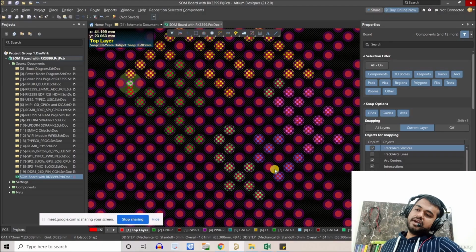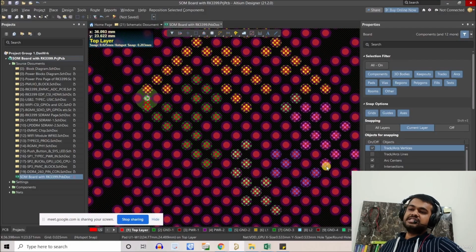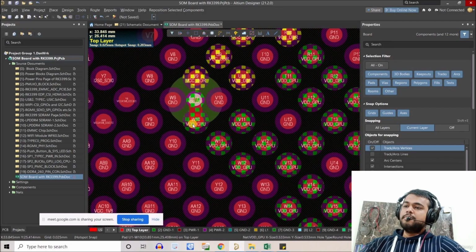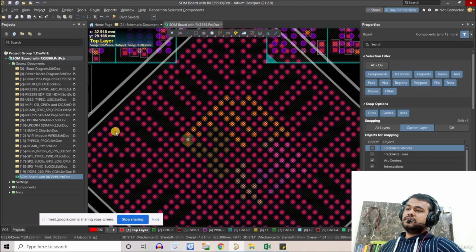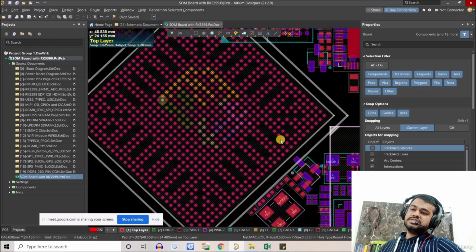So here we have fewer pads, only 6 pairs, but we have too many capacitors. In that case, we'll realize that 2 or 3 capacitors are more than the required ones, so we're going to remove those, because there is no point in packing everything, and that can impact the other fan outs as well, because here we have all the byte groups. Here we have all the high speed tracks of type C, HDMI, PCI in this section.